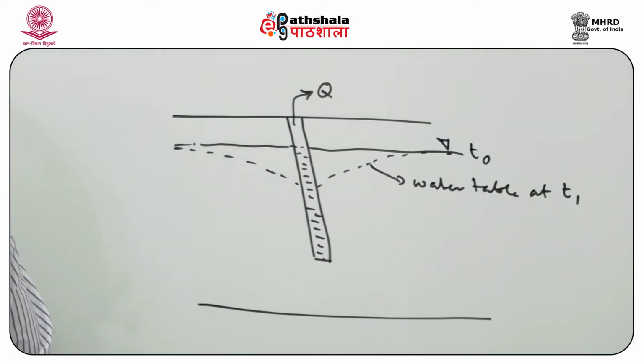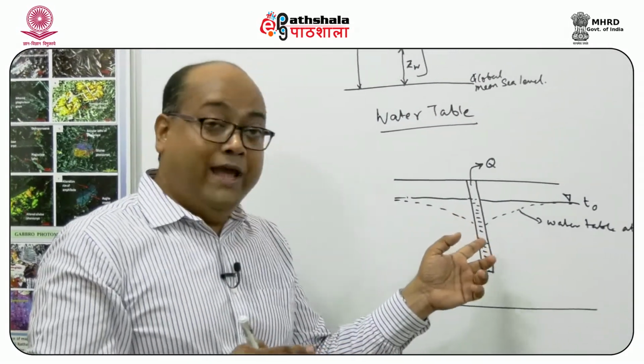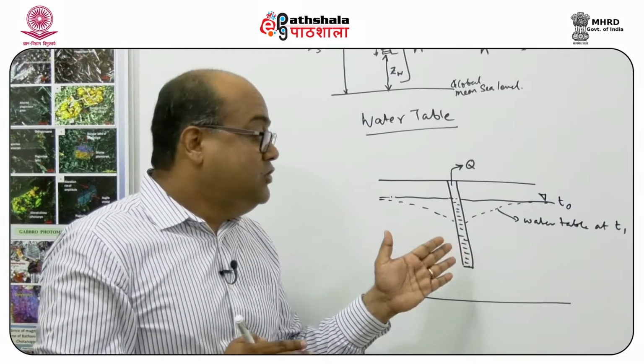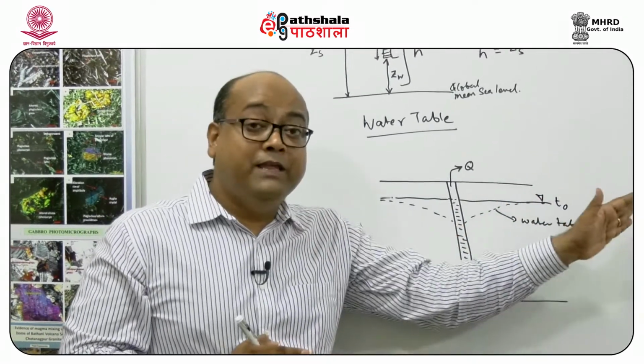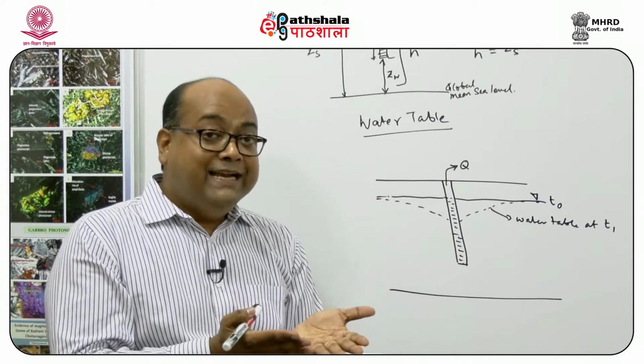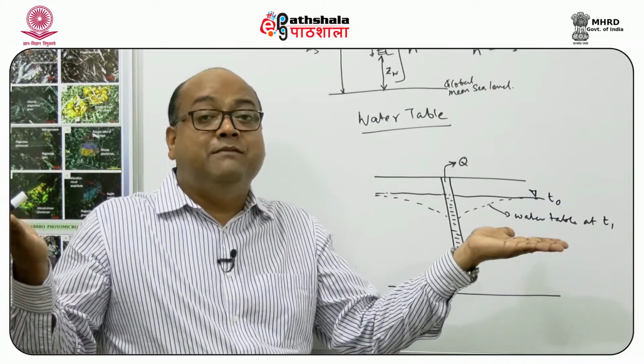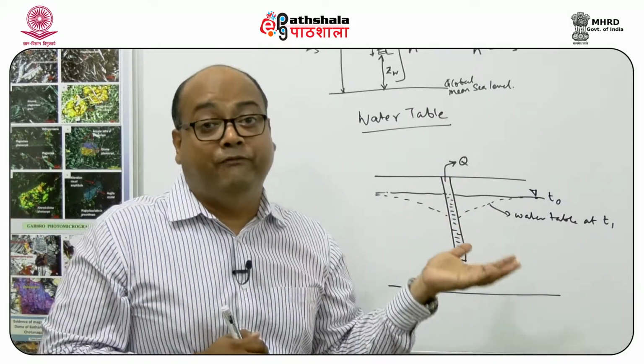What we can see is that there is a depression forming near the well, and as you move away from the well from which pumping is taking place, the water level becomes very similar to the static level, the level before pumping.